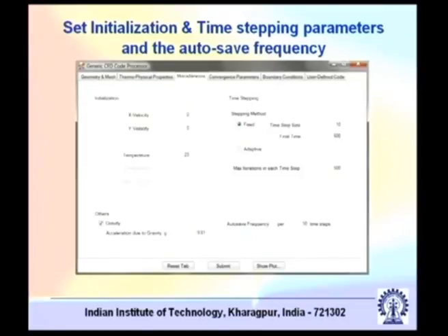So you have a gravity option, you just click the gravity option here and give the value of acceleration due to gravity. Remember, y is positive upwards, so to make sure that you are implementing the gravity along negative y, you give g as minus 9.81, but it is not always necessary. You have to understand what is there inside the code.